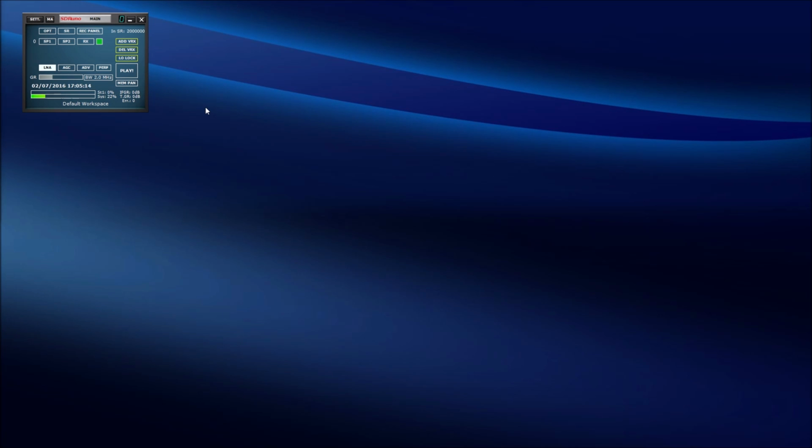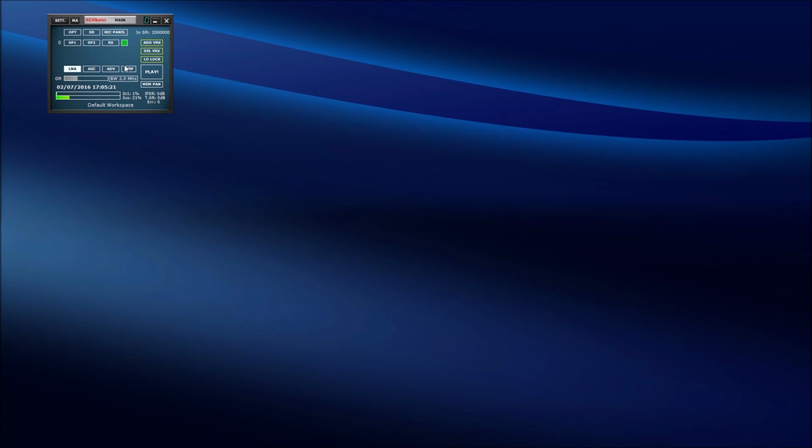I'm just going to explain some of the functions of these windows in more detail. When you start SDRuno up, you just get the one window. It's called the main window. We've embedded some of the RSP functionality into this window, and so when you start up the application, if you cannot see these four buttons, LNA, AGC, Advanced and Performance, that means that it hasn't recognized the RSP.